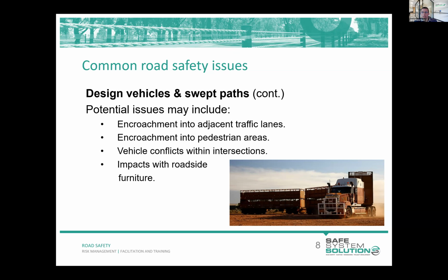It must be able to navigate the intersection, but perhaps not in a desirable way, or usually not in a desirable way. So it'll make some hook turns and swing across the road, mount the islands and so on. And if that vehicle is required to mount an island, that's where you do need to pave within those islands.